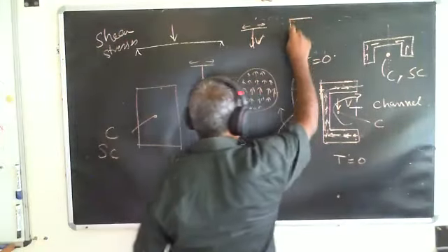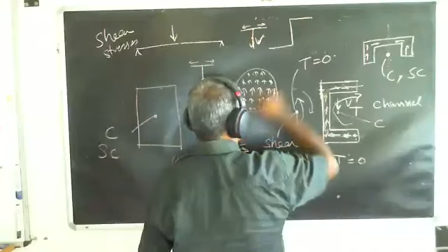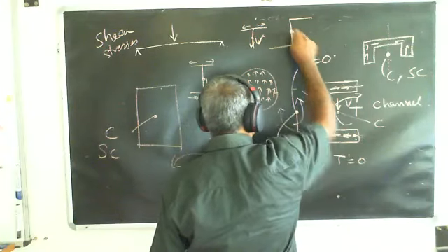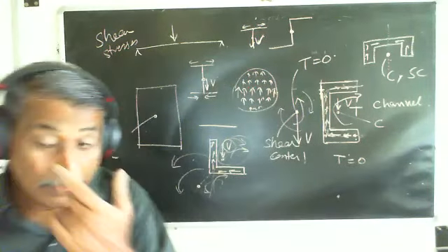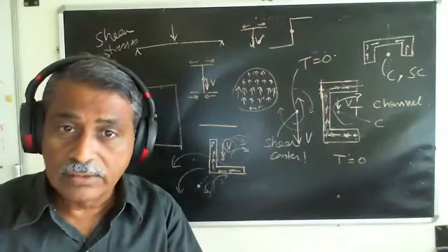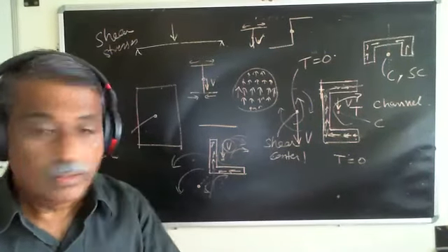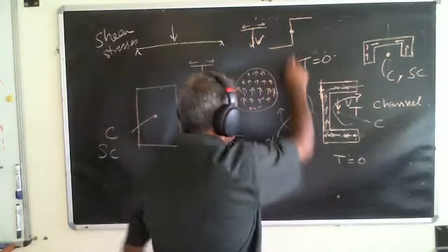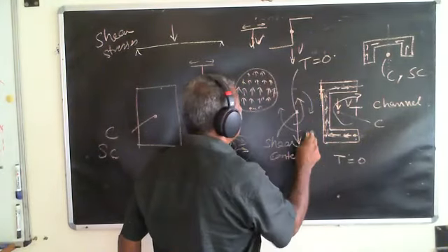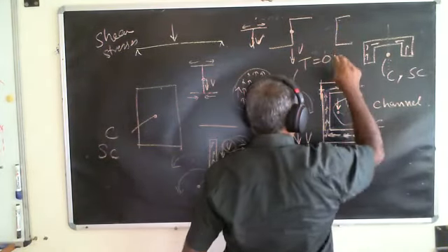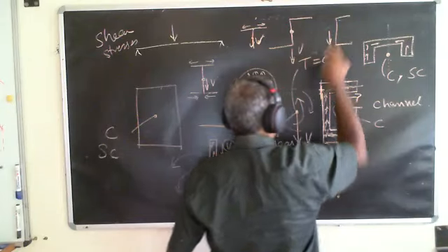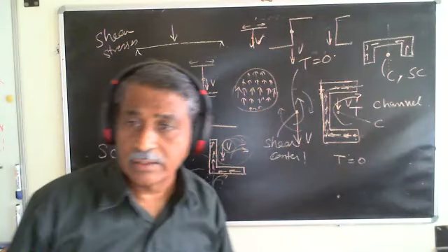Supposing I have a Z-like cross section. Okay, the centroid lies over here, right? Find out whether shear center lies over there. Okay. So would this be better if I have to apply the shear in this direction compared to something that is like this, where I have to apply somewhere away from the cross section?